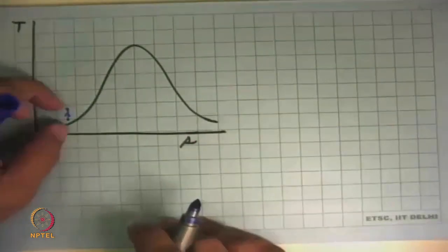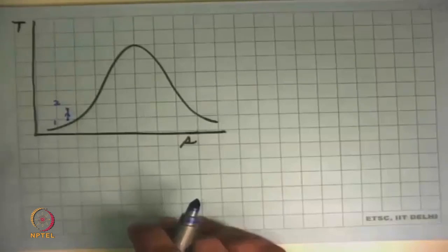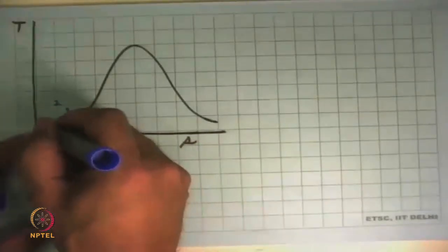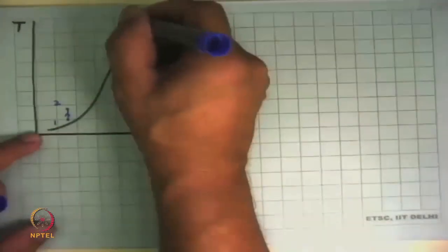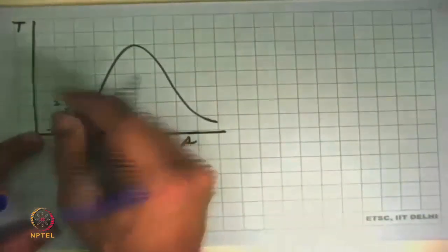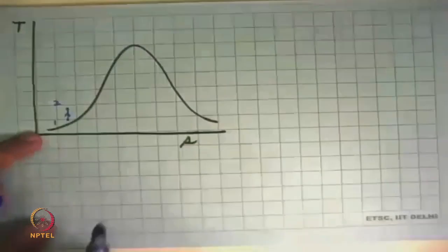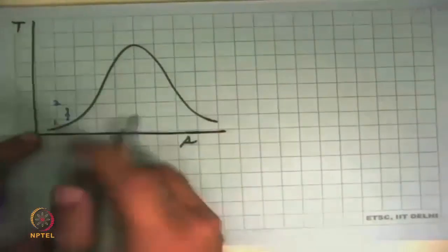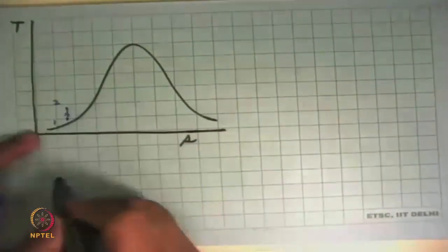I am exaggerating this, because as I showed you the TS diagram, the lines of 500 or 50 megapascal are pretty much very close to this, and so if I actually had to show this diagram, we couldn't even show it, simply because the effect of pressure on properties is so very, very small. But here we have done some exaggeration and showed it to clarify that the inlet state is compressed liquid.